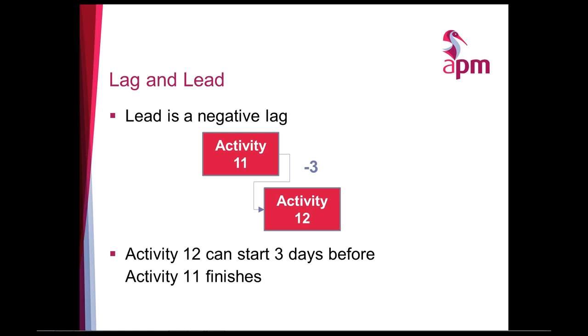I suppose just when we start talking about logical relationships, I think it's important that people have in their minds the idea that if you were to take activity 11 and move it and delay it, that relationship would move activity 12 with it. So just remember the purpose of putting these relationships is that if one thing moves in time, the other thing is affected by that. Exactly. Yeah, that's a good point to make.